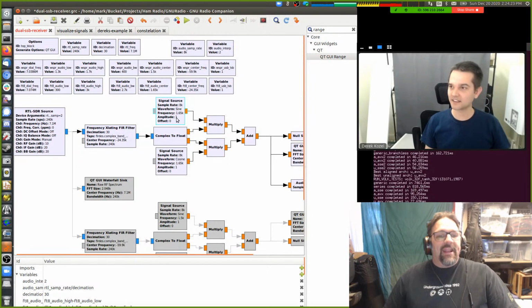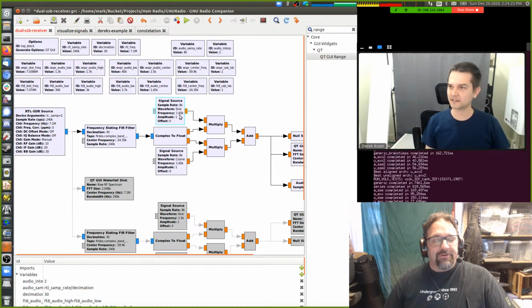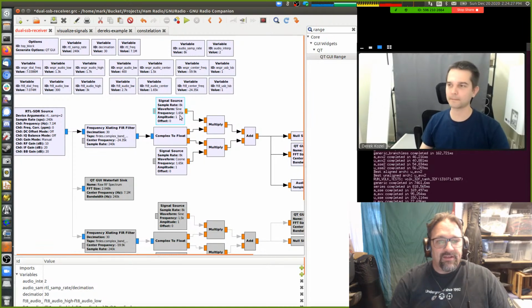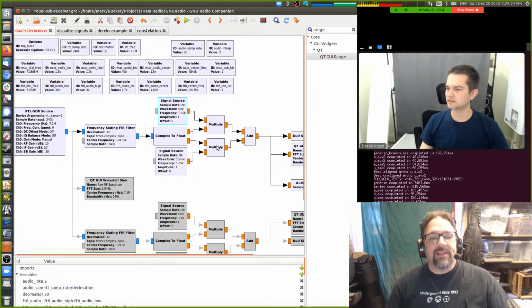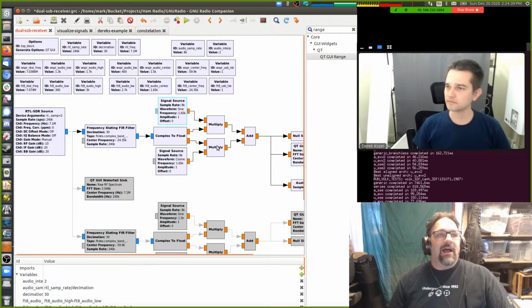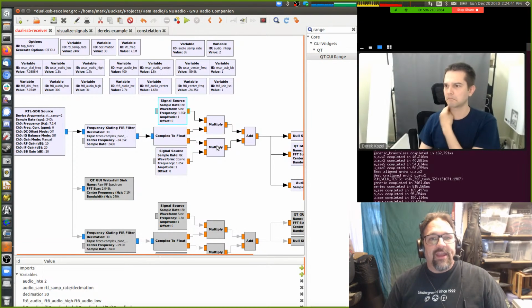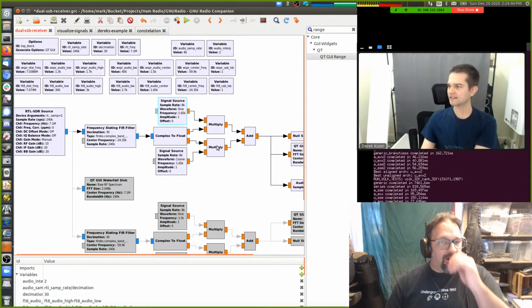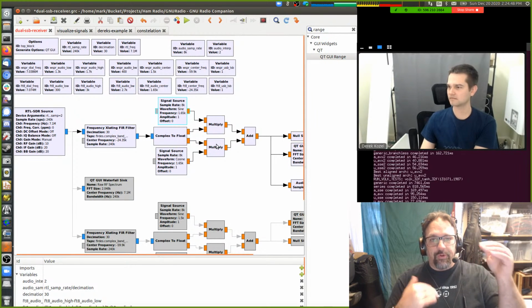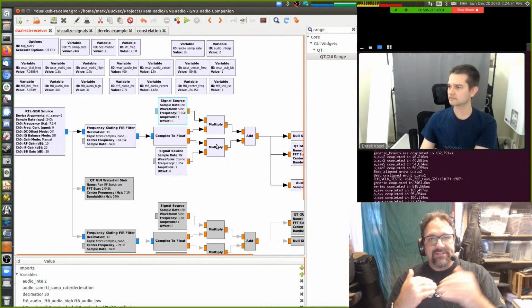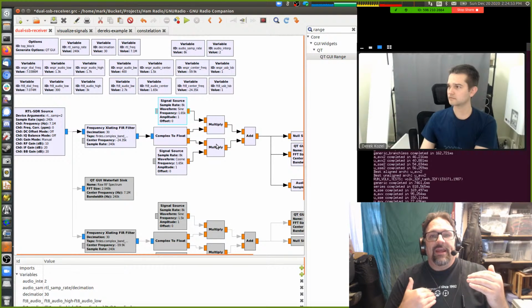Anyway, so we've got these quadrature signals that are generated smack dab in the middle of the audio passband. And then we feed those into our product mixers. Remember, a product mixer is literally a multiplication of the two signals. And if you look at the electronics of a product mixer in a conventional hardware radio, it is multiplying the two signals together. Like if you represent the voltages of those two incoming signals as numbers, their amplitude, the output of it is the multiplication of those two values.